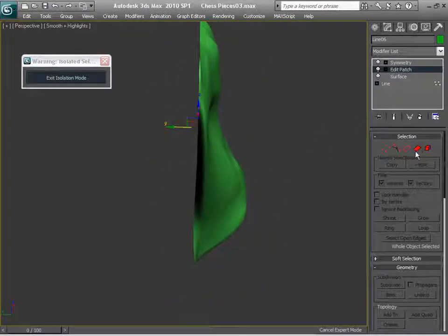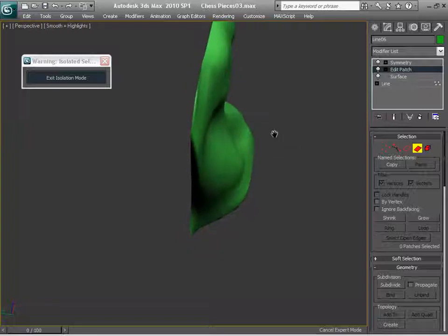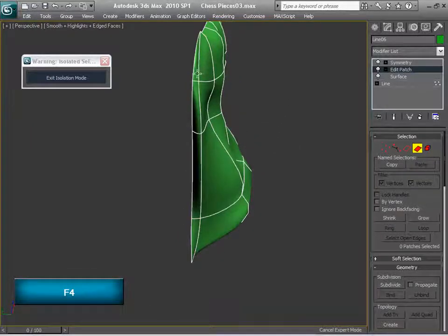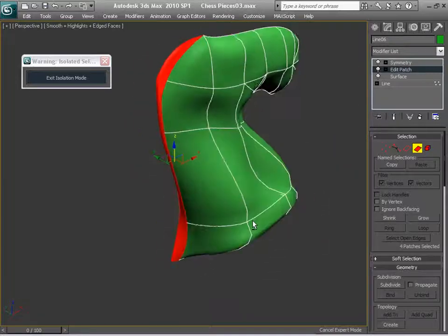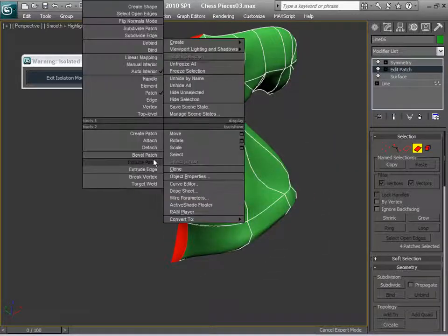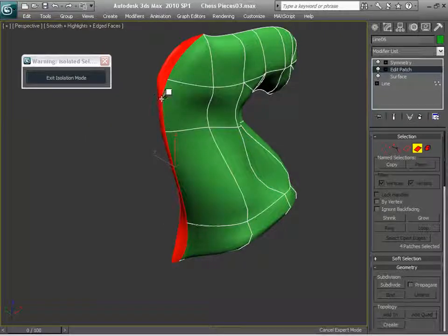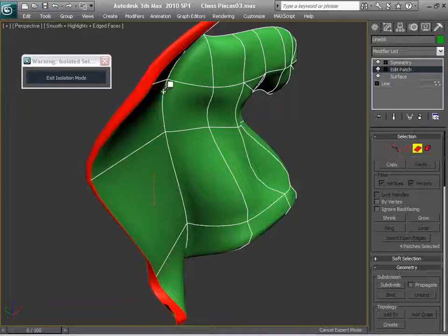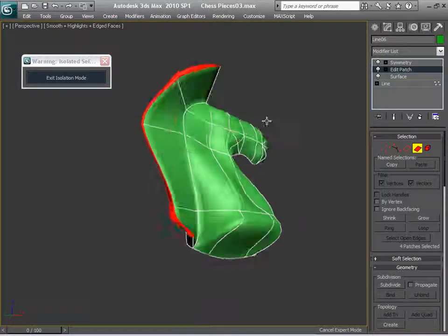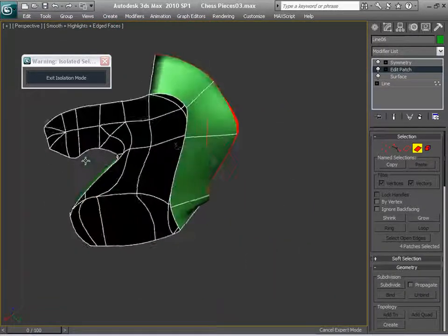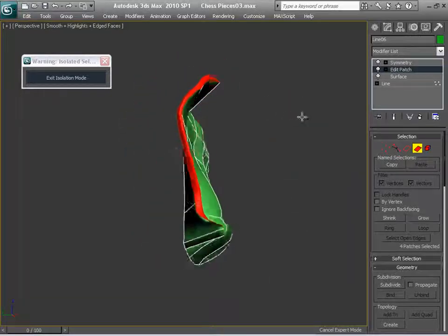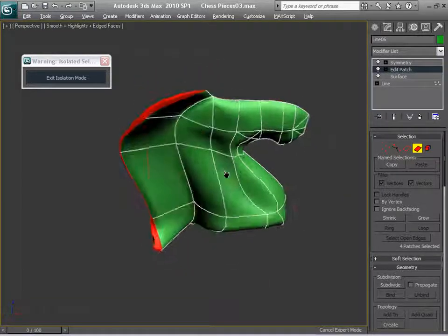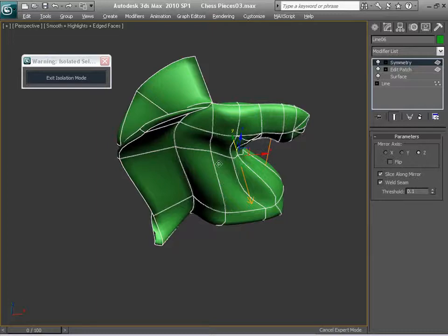So we're gonna select the faces. Go ahead and select and see those faces. And what we're gonna do with you is that we're gonna right click on it and we're gonna extrude the patch. And that way we're gonna get this. Let me see. It doesn't look that cool right now yet because it's bent. But, and this is where it becomes very fun, when we go up, this is what we get.